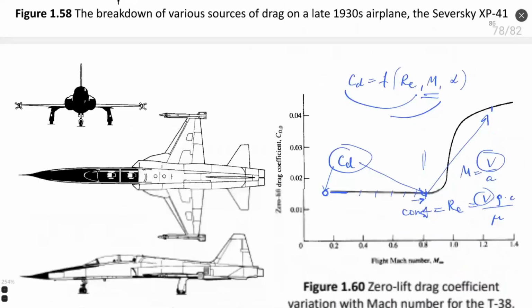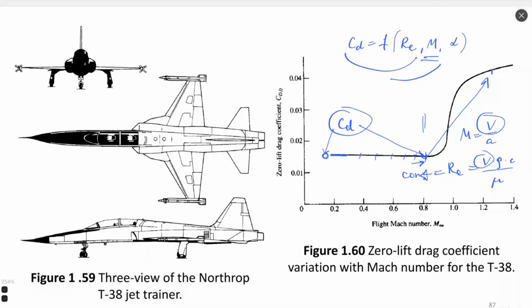But if you have constant Reynolds number, you can just change Mach number. It does not influence at all. So when you fix Reynolds number and try to change Mach, you will see no dependence. It means that we can test at small value of Mach. We will receive the same drag as for high value of Mach, until transonic flow, of course.